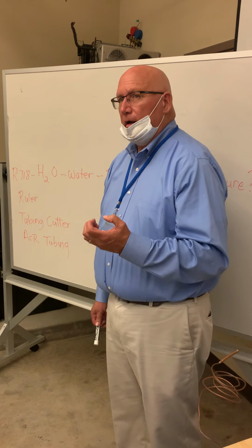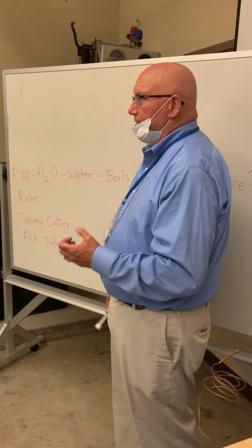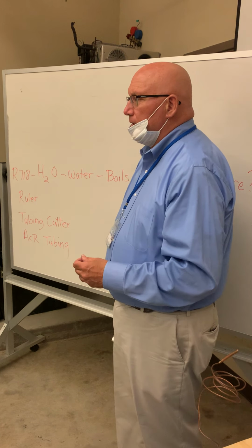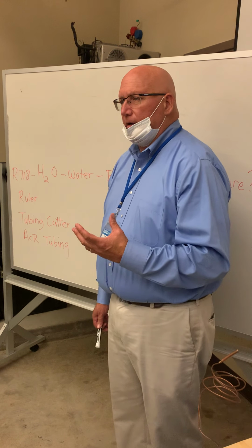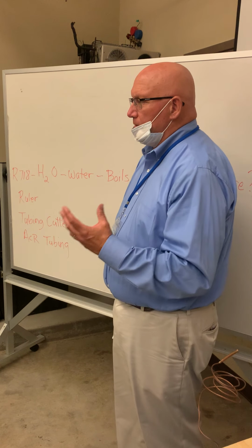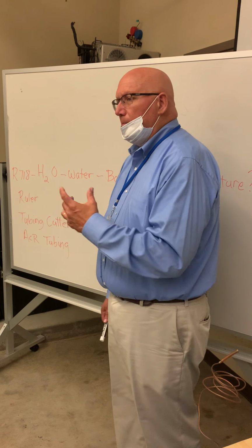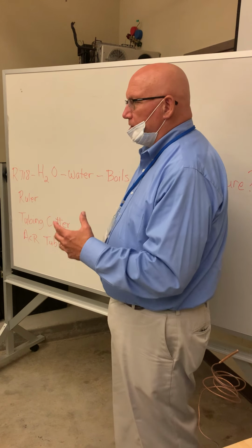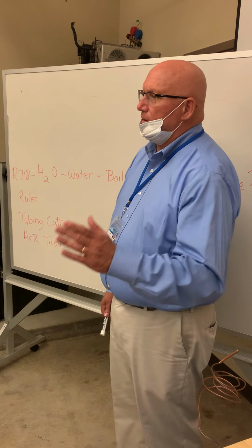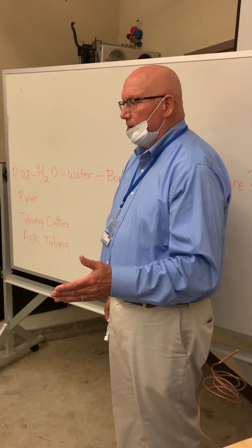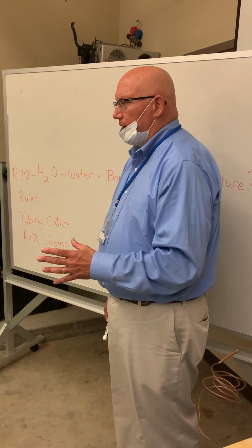Every one of our units of any kind, whether it be heating unit, cooling unit, they carry enough current that will absolutely kill you if you get electrocuted. Most people don't get electrocuted. Electrocuted means I was killed by the electricity that I received. Most people get electric shock.